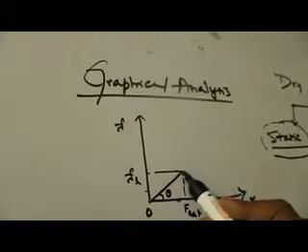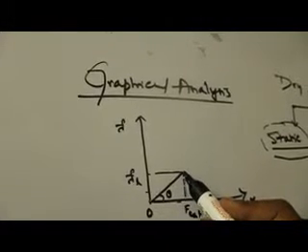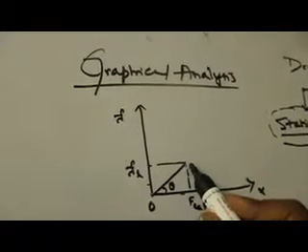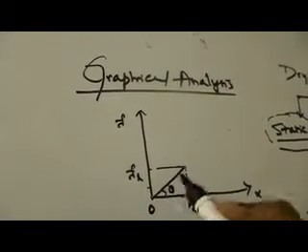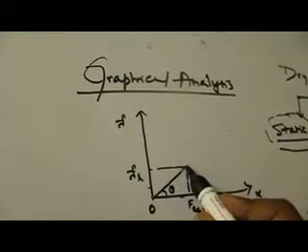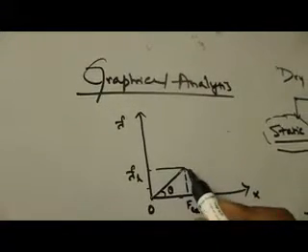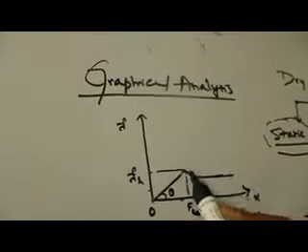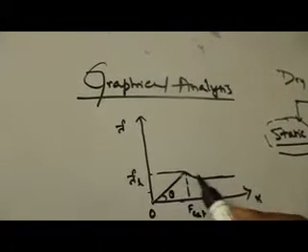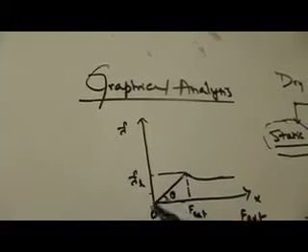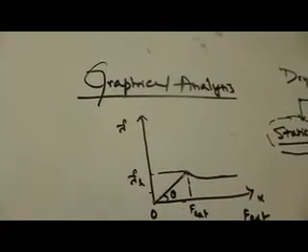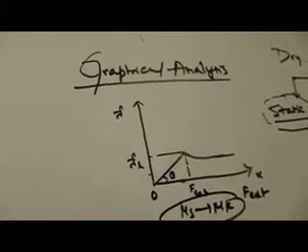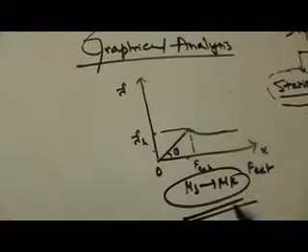Once it reaches this limiting frictional force, the particle starts moving, and after the particle starts moving, the static friction turns into kinetic friction, and there is a decrease in the graphical curve, and it looks like this, and later it remains constant. The decrease in the tangent slope of the curve implies that the coefficient of friction has changed from mu s to mu k, which implies that there is a decrease in the frictional force. That is what actually happens.